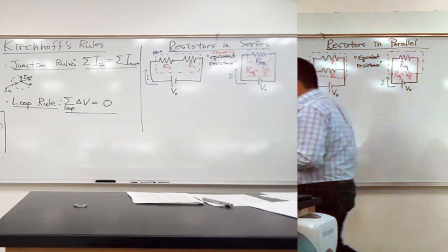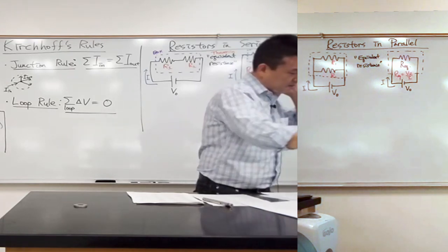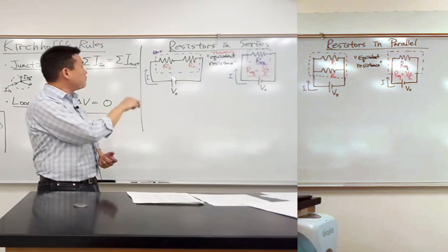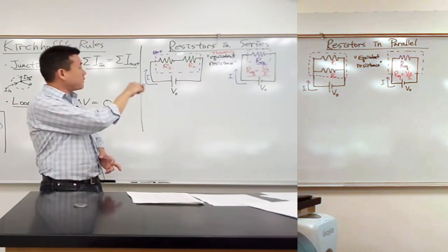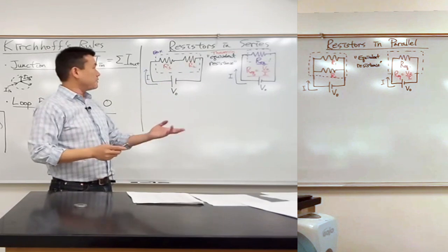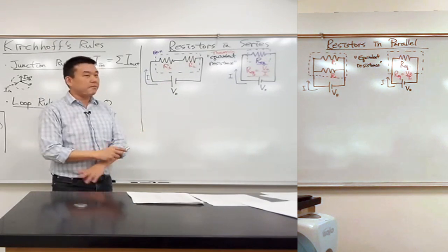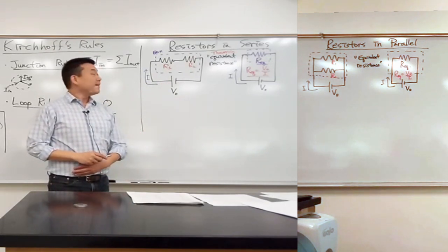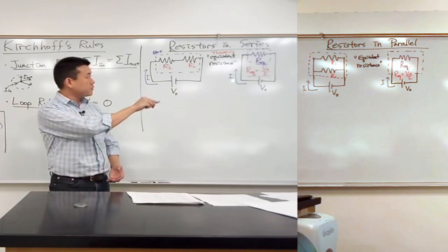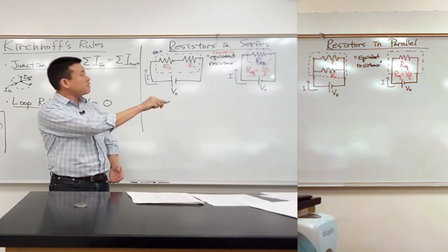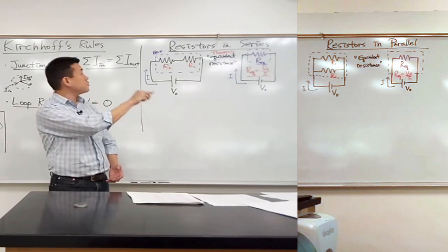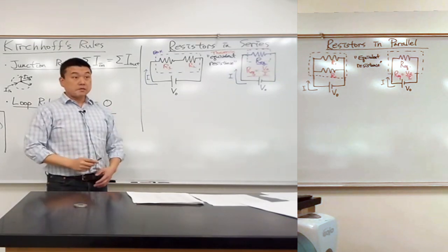And the theorem that Thevenin proved is that as long as your circuit consists only of resistors, then no matter how complicated it is, you can reduce it down to this. There's one more part to that theorem, but we'll go into that later. So we are going to try to find the current, and once we do that, we'll put it in here, and we'll try to express this equivalent resistance in terms of these resistances alone.